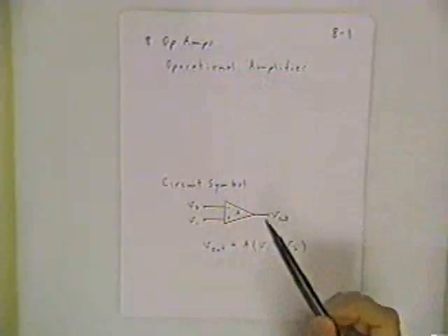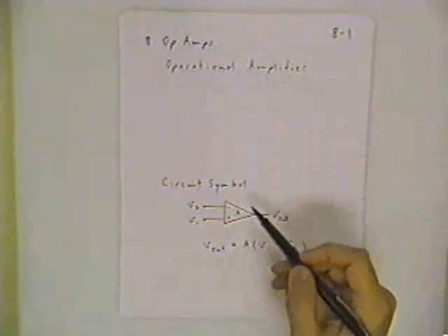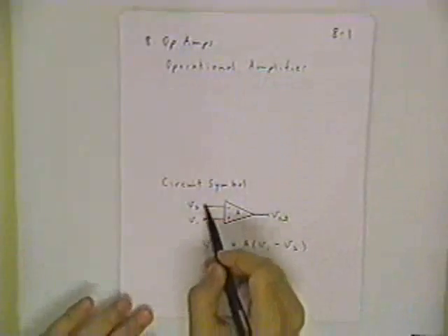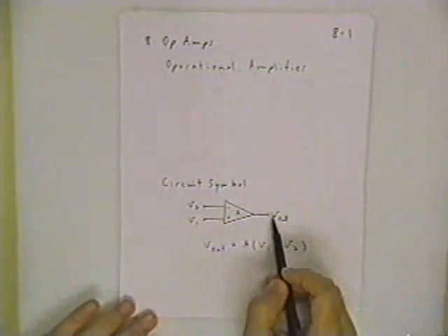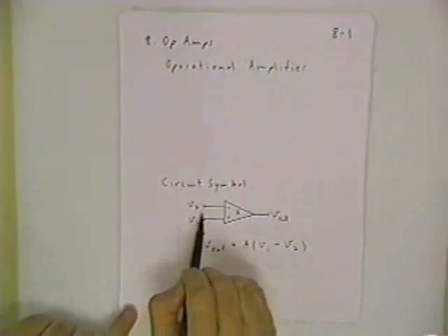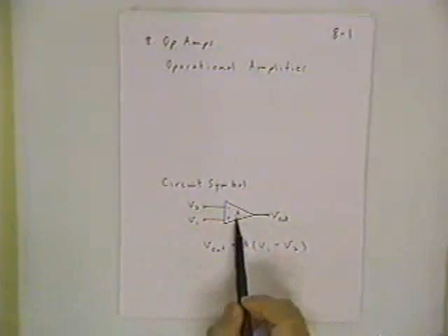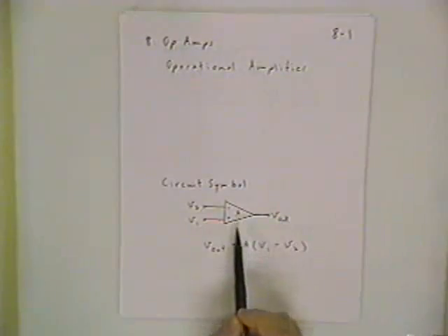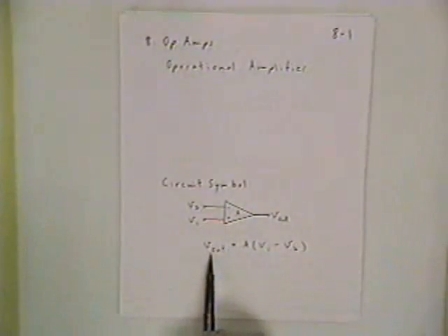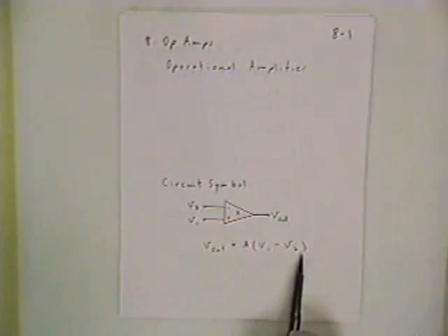Now, what an op-amp can do for you is take an input signal and amplify it, but where this is most useful is taking the difference between two input signals and amplifying that difference with a magnitude of A, called a voltage gain, and it's not accidental that this is the same letter we used for our frequency response. Vout divided by Vn was also called A. This A is called the open loop gain, and the equation relating the output to the inputs is what you see here.